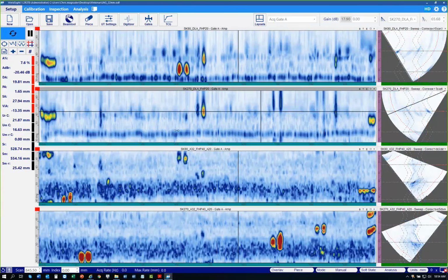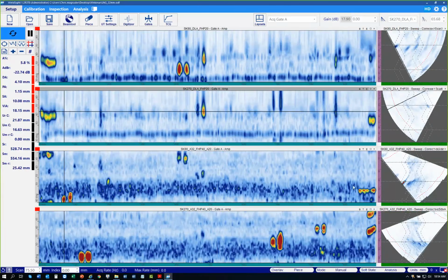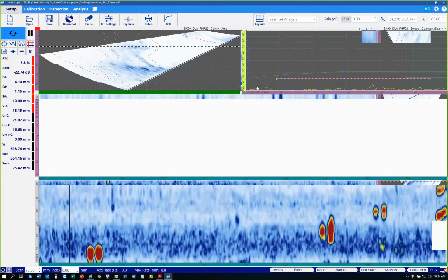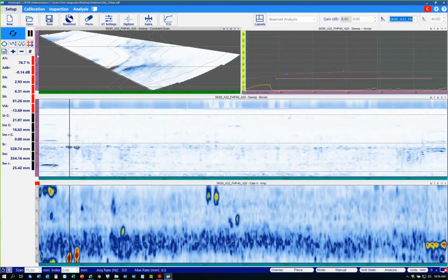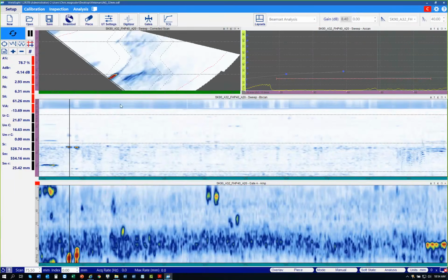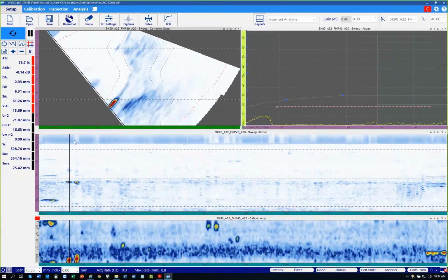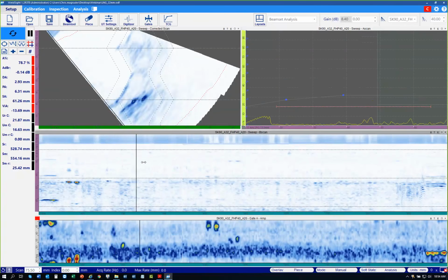The benefit of the shear wave inspection, like we see right here, is for all of the bevel flaws. We have to prove a lot of accuracy during the qualification tests, and many of the flaws are bevel flaws. The 4 megahertz probe is uniquely suited for the Inconel inspection. We can see the weld bevel right here.